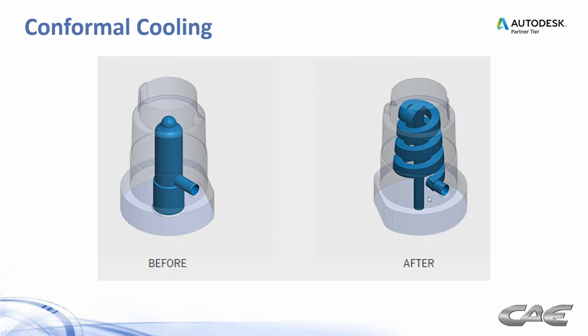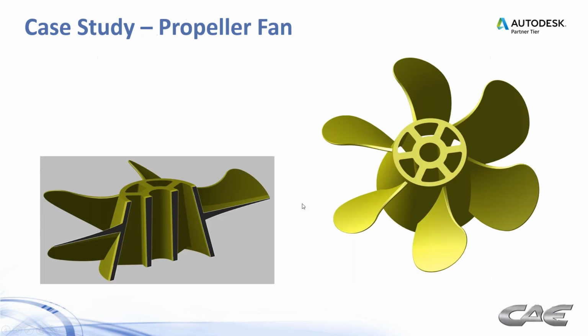You know, with conventional designs, it's often difficult to get those cooling channels so close to the surface. And remember, when we talked about depth of channel from the surface, depth controls a lot of that temperature variation that goes on. So oftentimes when you get closer depth, you have to put the cooling channels a little closer together, or else you get that temperature variation that you don't want.